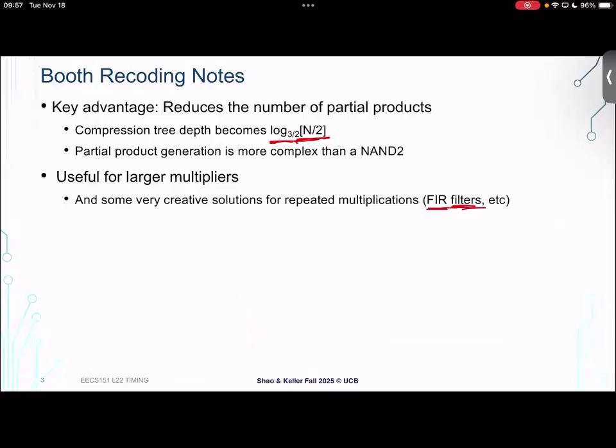So it's kind of like past radix 4, the costs go up like this and the benefits go up much more slowly. So I would say in practice, radix 8 would be possible, but rare that it would be optimal. And then past radix 8, it's almost certainly not going to make sense. That's a very good question, though. Yeah, in theory, there's no reason you couldn't design a multiplier like that. For large multipliers, I would say radix 4 often ends up being the best design for performance.